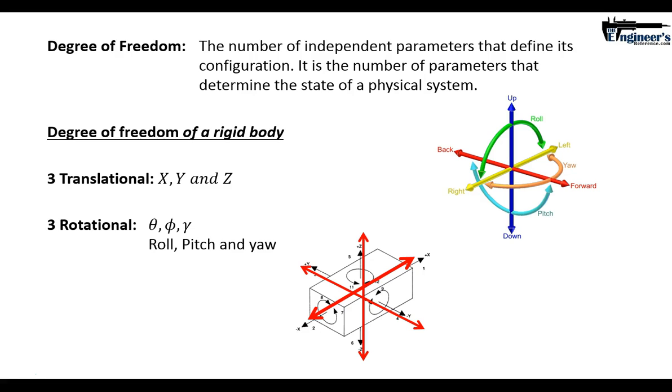Now, I want you to think of that phrase there, a rigid body. Each one of the links in that robotic gripper was a rigid body. The 2 claw ends were rigid bodies. The links that connected it were rigid bodies, and the gearing system was a rigid body. Each one of those, unconstrained, has a degree of freedom. Now, what's the key here? They weren't truly unconstrained. They had something that constrained them together, something that helped them get from just being a free to move physical body to being something that had a purpose behind them.